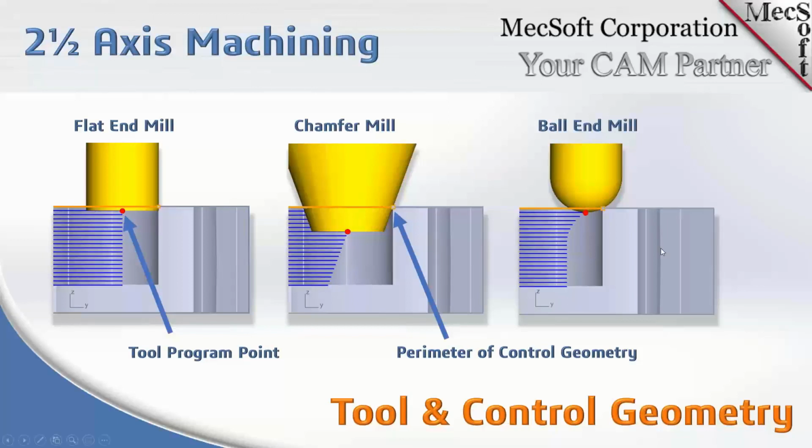So typically you won't use a round ball mill for a pocket. Now for profiling, if you're just going to cut at the bottom of the pocket, if you want to leave a profile in your part, you can use a ball mill and just run it at the bottom of the pocket around. And actually our part that we're going to demo uses a corner radius mill that incorporates the radius into the part, and I'll show you that. So these are the basic understandings.